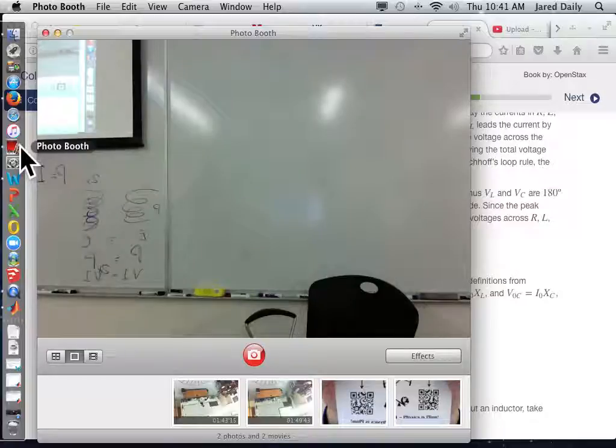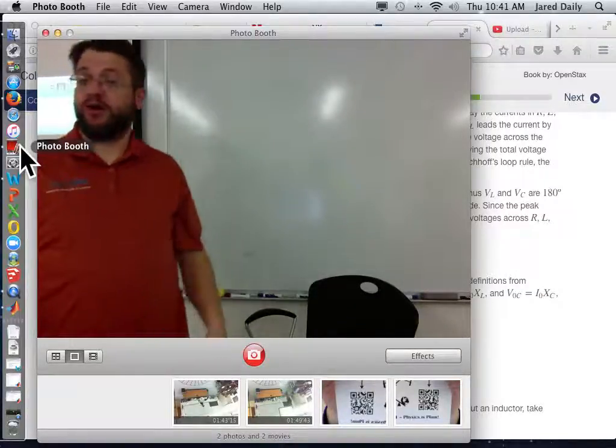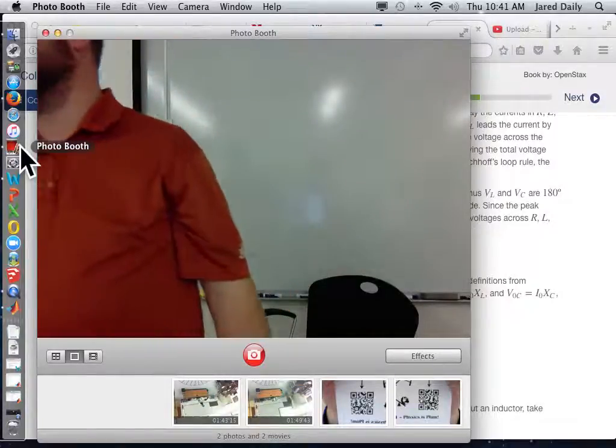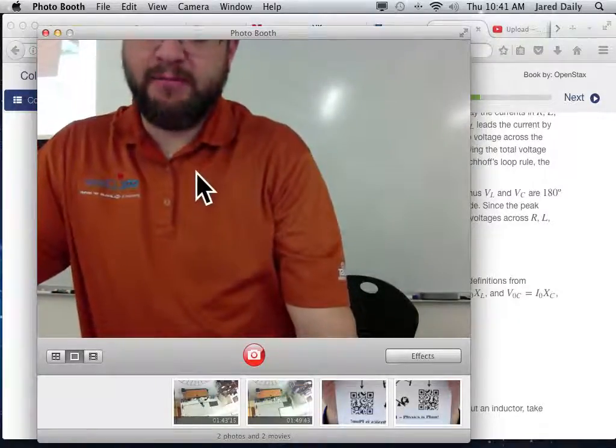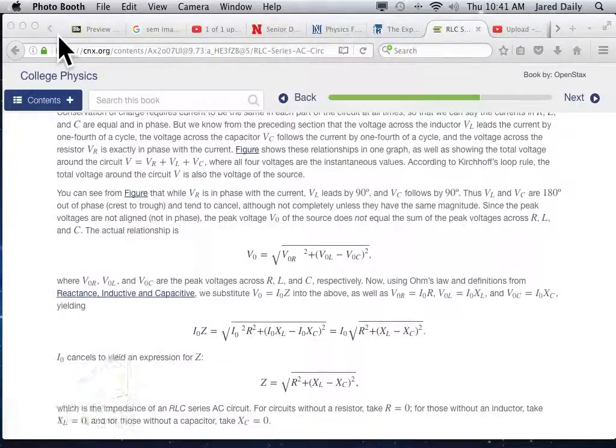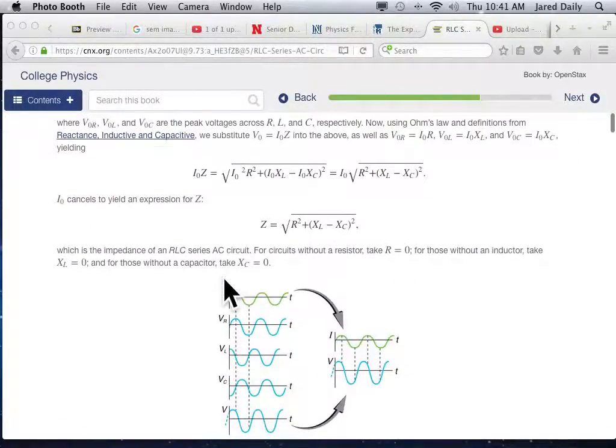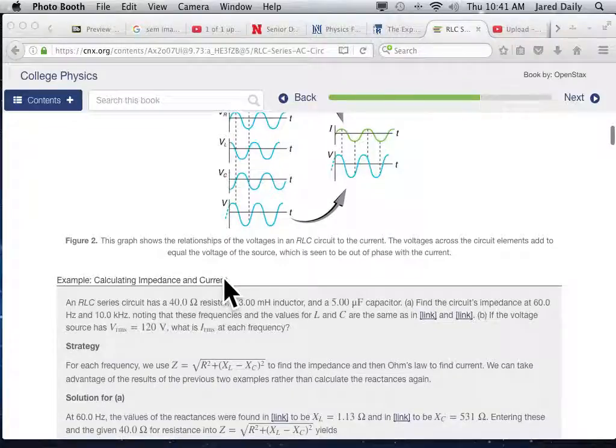So this has an overall inductance, and it's designed to have an overall impedance. And they designed it specifically to have a particular impedance so that when you're using it with another instrument, you know what kind of resistance or impedance that this thing adds to the system. And that's the impedance of an AC circuit. And again, you can use this in Ohm's law. Ohm's law is V equals I times R, but in an AC circuit, you replace that R with Z, which is the impedance. So it's V equals I times Z.